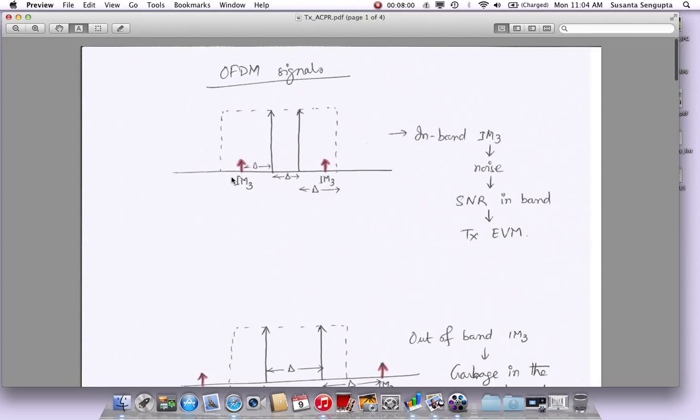If you had 1,000 subcarriers and they all were in phase at the same time, that is, all the 1,000 sine waves line up with the same 0 degree phase, and all of their phases match up, then of course, at peak, when the sine wave peaks, 1 plus 1 plus 1, you will add up and it will become 1,000 volts, right?